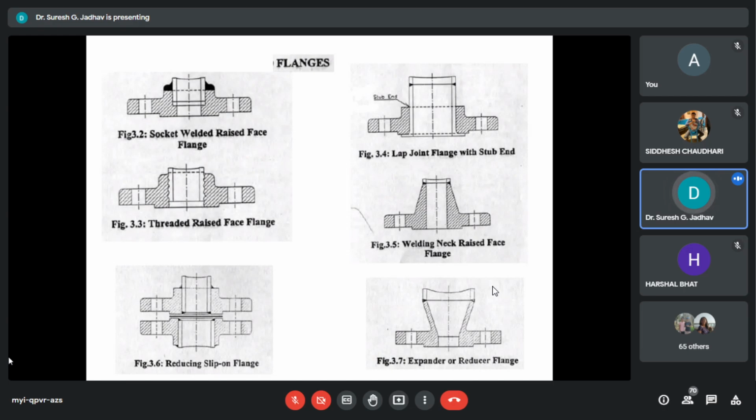Flanges are used when the joint needs dismantling or disassembling. These are widely used mainly at equipment, valves, and special fitting components. In certain pipelines where maintenance is a regular feature, breakout flanges are provided at definite intervals on pipelines.